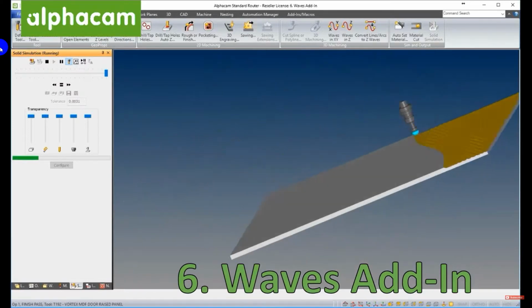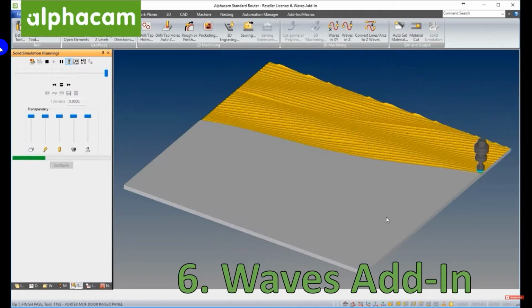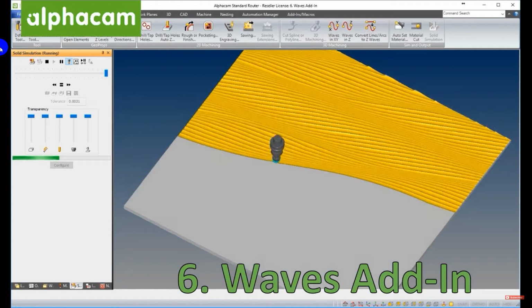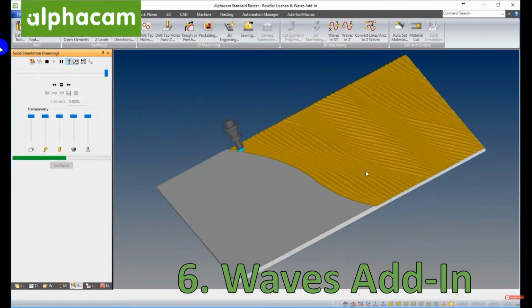We're achieving this interesting and compelling looking pattern by simply using rough or finish on the geometries that were created by the macro. And I'm sure you'd agree with me, this looks really, really interesting. Understanding this is nothing but a bunch of lines and arcs that happen to be machined with a ball end.